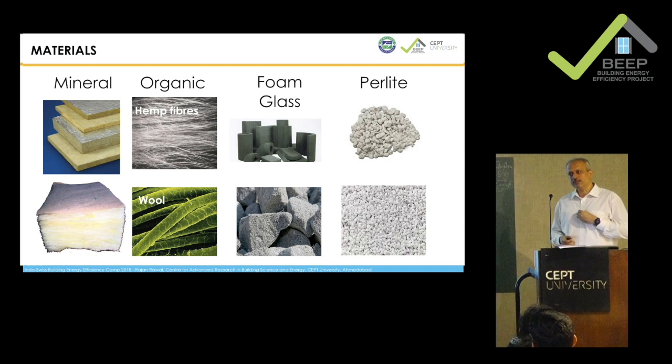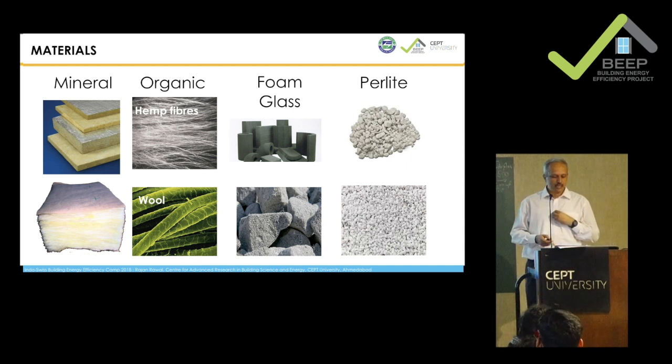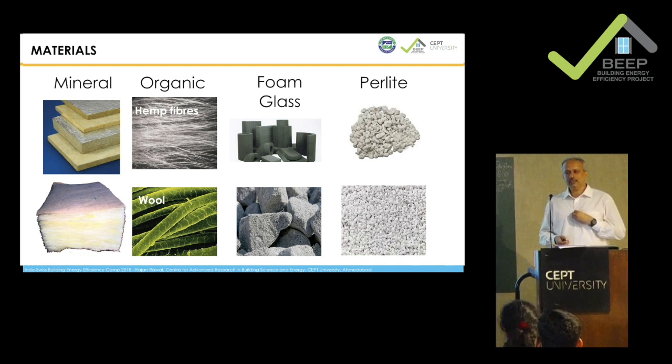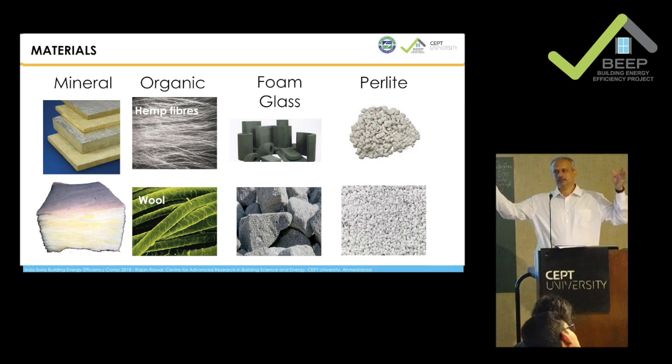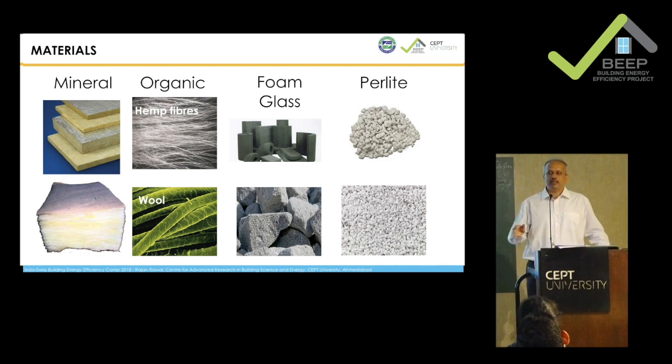Now I have a question for you. We were talking about something like this, okay? And now we know that we have these materials. If I have to cover this space with insulation, and assuming that this is a 100% 24/7 air-conditioned space, we are not going to open windows, where will you put your insulation?